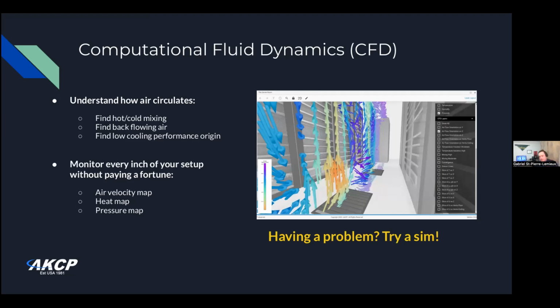So why do you want computational fluid dynamics? It is an analytical tool that allows you to see what happens far from your probe. You have probes on your rack and on your CRAC, and you don't want to put probes in your vents, at the door, everywhere. You don't want to put an anemometer; anemometers are really expensive.